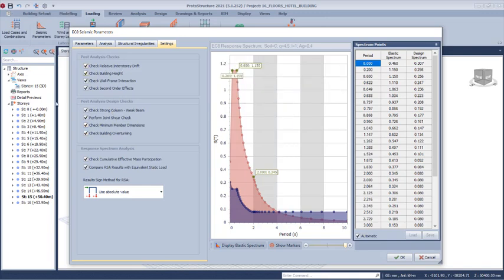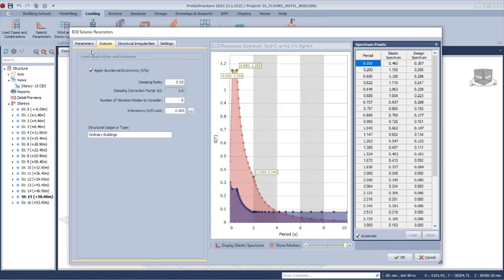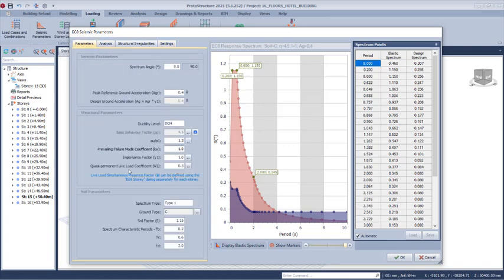The program will detect all of this, and if there's an issue, it will pop up and give you a warning. So if you feed in all of these appropriately, you may not necessarily have any issue with your structure. That is why I said you must have the report of the seismic parameters, the report that contains the seismic parameters, which is the earthquake report of that construction site.